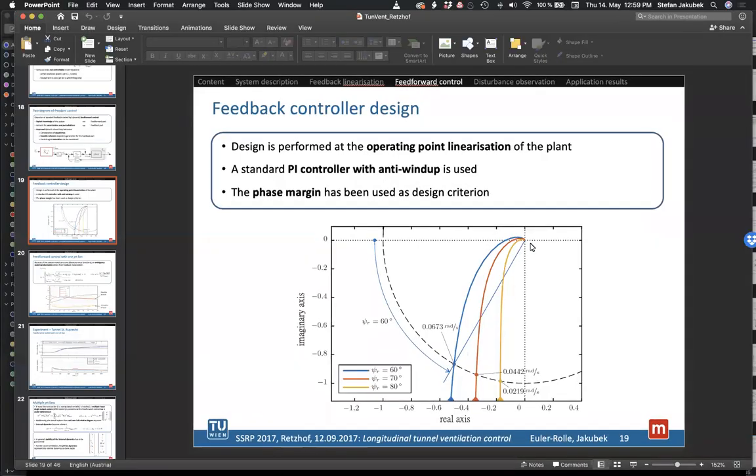The way you probably remember it from the Grundlagen der Regelungstechnik, which was actually PI control with phase margin. So this was Phasenreserve, if you remember it from German. So you probably know this way of controlling it. This is a way of controlling or designing controllers in the frequency domain. So depending on certain controller configurations, you get more or less phase reserve and overshoot and so on.